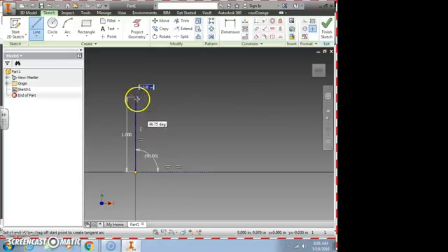You can also just drag the line over, and then you can come back and change the dimension. So I'll show you that. When you type in the dimension, it is actually shown there on your sketch mode. It's not the same thing as dimensioning like you just finished in Chapter 9. This is just telling me that's the length of that line. Okay, so you don't have to go back and list it. You don't have to go back and click on dimension to see what you drew it as. It just stays right there on your screen.